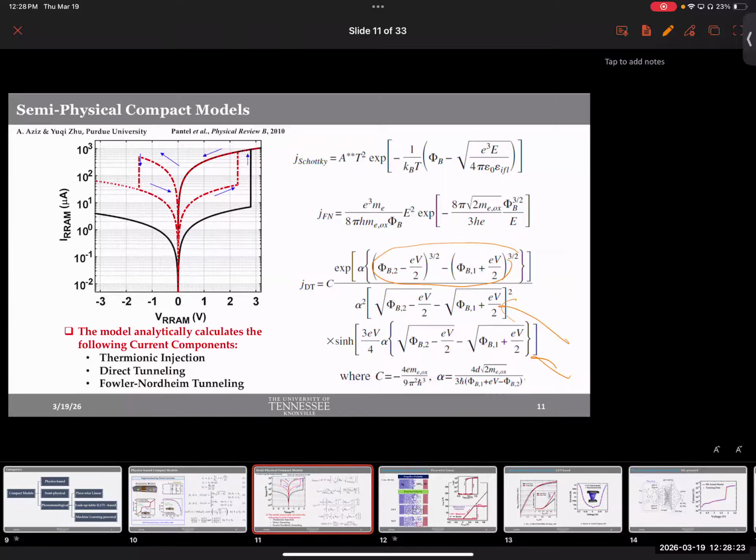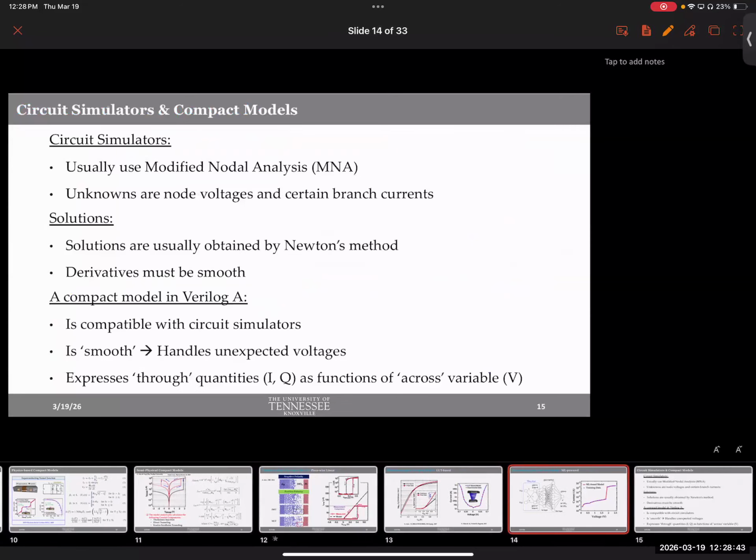Here, I'll put 1 pico times 10 raised to 12 that I artificially introduced, and then I will again multiply it by 10 raised to minus 12 to get rid of the scaling factor. Now that everything is in the mix, they will be treated together. They will not be ignored individually. So that is a technique that people often use, and have to use, in many modeling approaches.